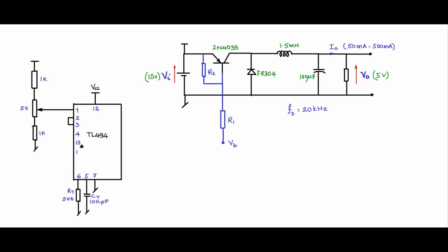There is a steering pin and the other error amplifier's positive input. All these, let us ground it. We don't need it now. And the plus of the other amplifier, the minus of the other amplifier and the output of that one, we short it just like here in the voltage follower mode.